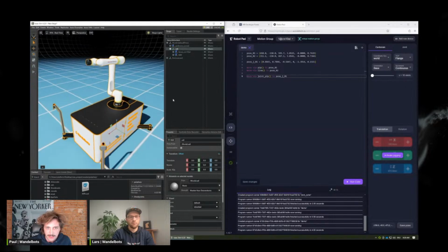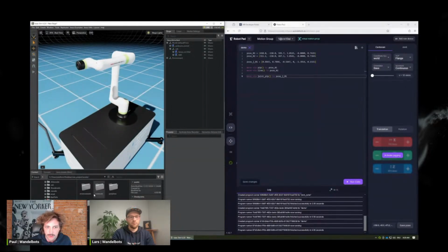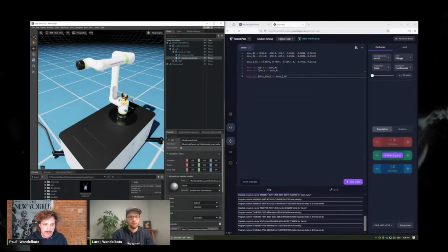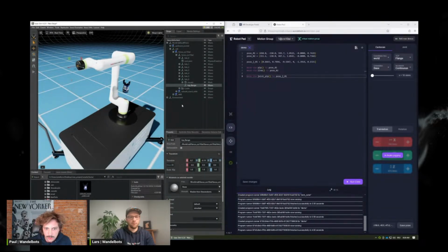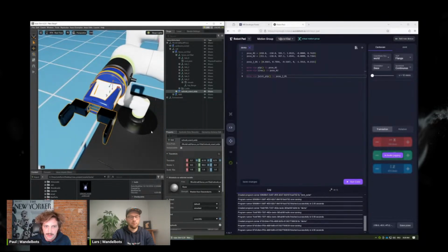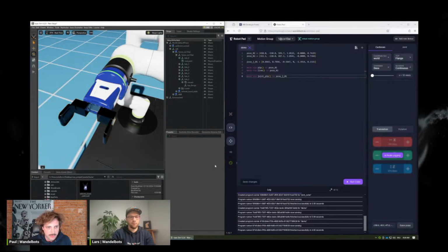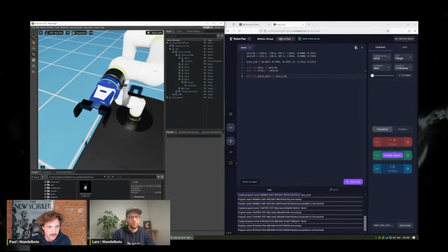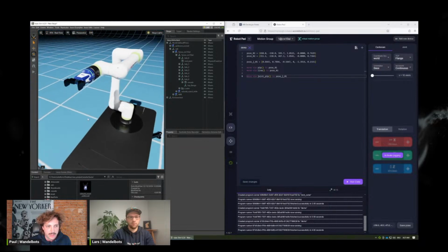I like to create this cell Xform where I put the robot and all the periphery. Like this, we have one cell in the end that we can move anywhere, that we can export, import into another scene, stuff like that. And now we imported the tool, and we want to attach this tool to our flange, of course. So we copy the transformation from the TCP. This TCP is already stored in the FANUC 3D model in our USD assets. And now I'm just doing some small adjustments here to this tool. So great, this is now attached to the flange.